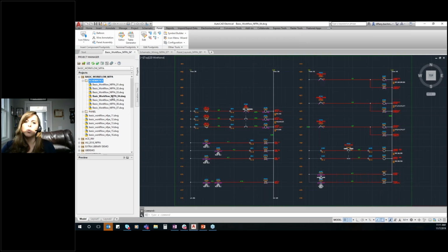So they're just a way for you to organize and quickly find your drawings, especially if you have those larger projects like the 100+ ones we were just talking about. It's just much easier to navigate. It also allows you to run project-wide commands on a specific group of drawings. Now you could manually pick them every time, but the beauty of the folders is you could say, I want to run a project-wide update on just everything within that schematic folder. So they're kind of like mini projects within the grander project. Lots of different ways to use those folders, but really good tips and tricks there.